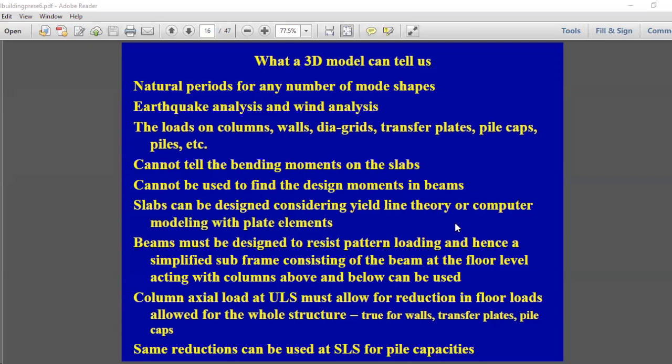Then the maximum load that you can get on the slab is about 2.5 kilonewtons per meter square. But when you are designing, we design it for a load of 5 kilonewtons per meter square. So you can see the live loads that are allocated have an allowance of about 50% for dynamic effects. When you are considering the full building, you don't have to consider this dynamic effect, because there's no chance that all the structures will have dynamic loads at the same time.